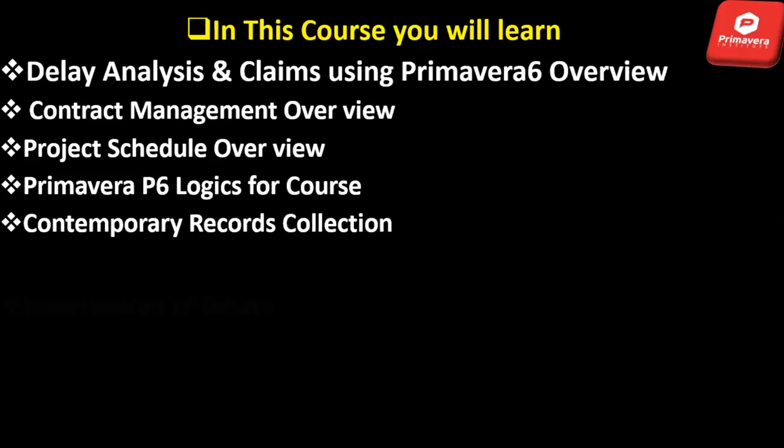Then you will go through investigation of delays, where you go through all the documentation and the actual ground-level situation at site, and investigate what kind of delay it is. That helps you determine which party is responsible for that delay.